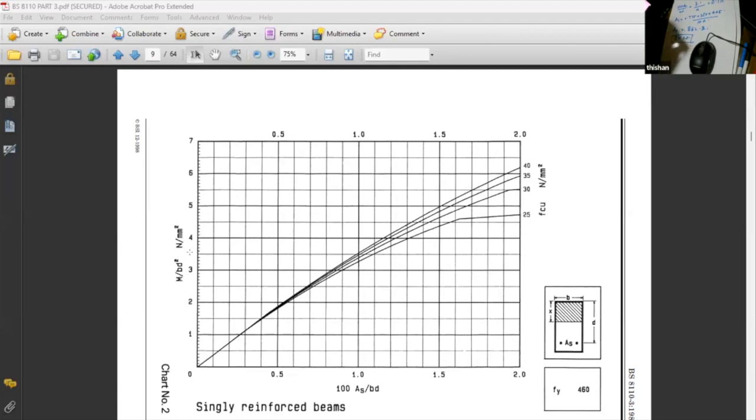Yes, sir, there are a few. One is, if we use welded mesh for a floor slab, what is the deviation from normal codes? No, nothing. It's a construction practice because the welded fabric is made to a standard, so you just put it. The only thing is you have to make sure the steel area is there.